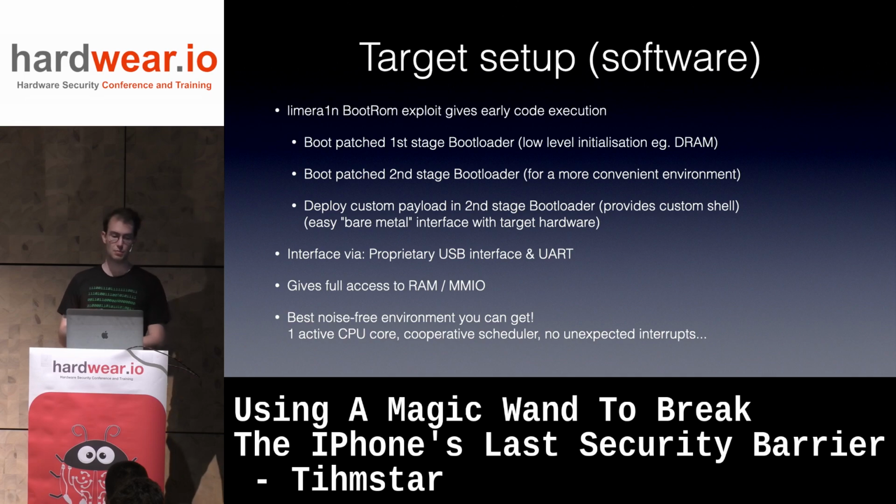It doesn't have a proprietary USB interface, and it has UART. You have full access to RAM and MMIO, and it's kind of the best noise-free environment you can get because there's only one CPU active, it has a cooperative scheduler, and it usually has no unexpected interrupts.